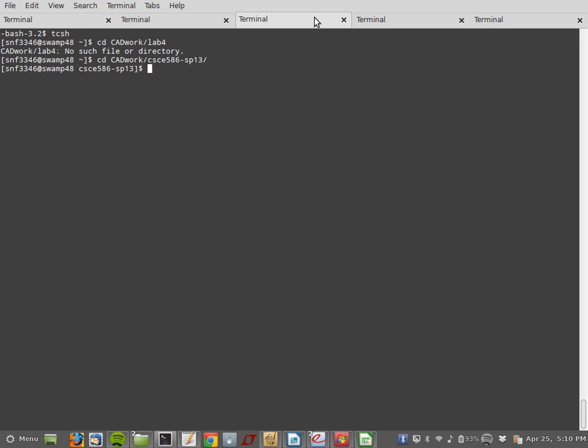So the steps are, as usual, you go to the directory you want and you write cat setup 45, the same thing. Now let us quickly create the Verilog file. Let me make an 8-bit adder, so let's call it adder8bits.v.